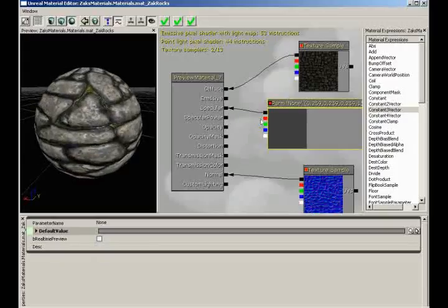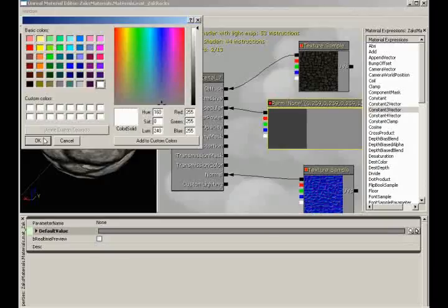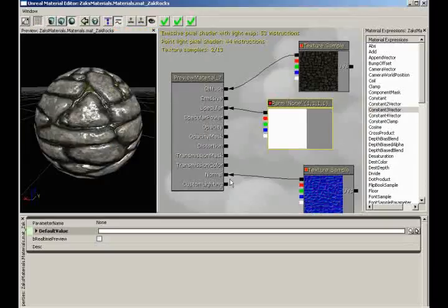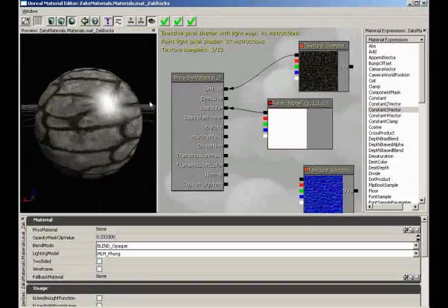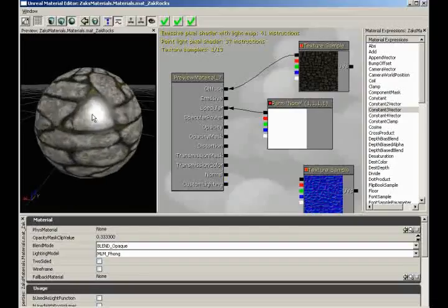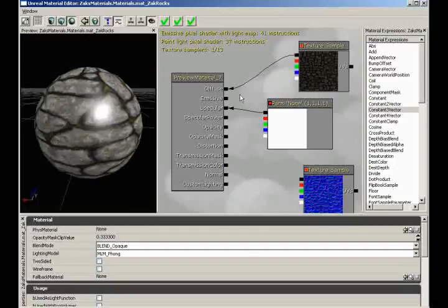Now, moving down from here, we have specular power. And to really drive that home and make it make sense, I'm going to do a couple of things. First, we're going to take our specular color. I'm going to set it back out to white. Then I'm going to hold down the Alt key and I'm going to left-click on the normal connection so that we break that again. And what I want you to pay attention to is the size of our hotspot here on our surface.